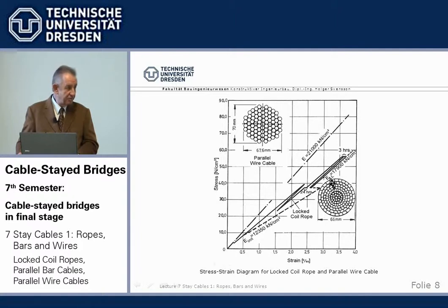Still away from 2.05, but still there. And then during the life of the bridge, this pre-stretched modulus of elasticity stands, and we end up, what I told you earlier, with something in the range of 17 instead of 20.5. That's the problem. It creeps, and it's not a real constant modulus of elasticity.